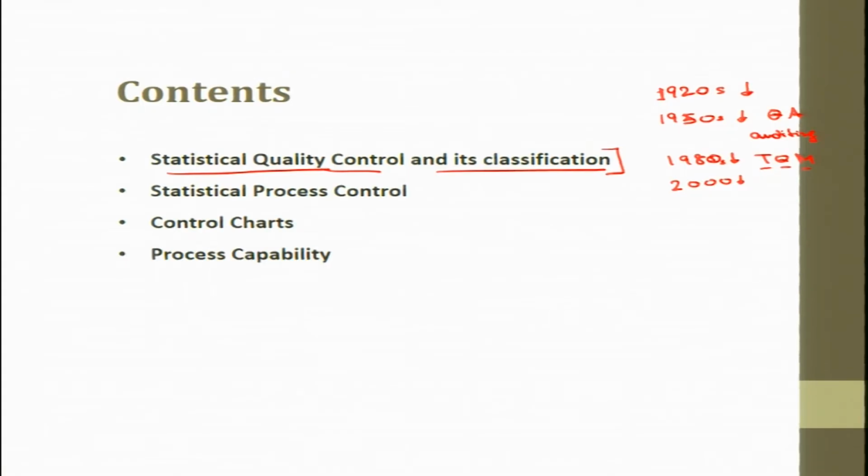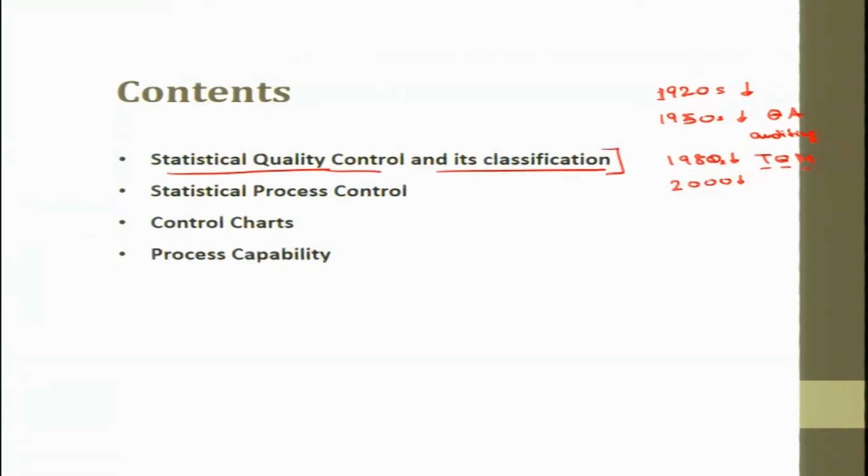In 3D measurements we can do measurements in 3 dimensions, like we can scan, and we'll take you to the laboratory here and see the coordinate measuring machine, and how 3D coordinates are measured. Rapid manufacturing, then rapid prototyping, which is now additive manufacturing, also came into play, and people are working on that. So quality control traveled through these milestones.